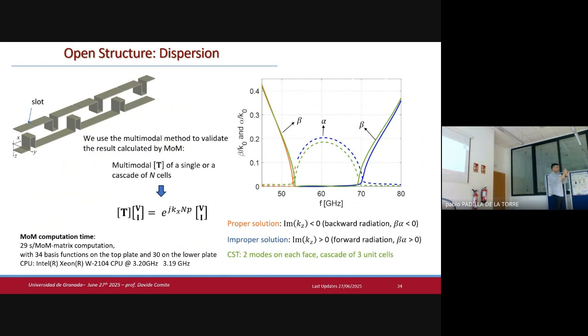Big alpha means that the exponential tapering of the leaky-wave antenna is very fast. When you have an exponential, if you have a big alpha, it means a big multiplication factor in the exponential, you get a very fast decay. If you get a very fast decay, the antenna will never be electrically large enough. So there is always this connection. So this one, we are studying it with Guido, Sorbonne University, and we are still having some problems, because it's not easy to control this alpha, because you start from a configuration where alpha is already big, because there was a stop band due to the fact that you were generating a periodic perturbation.